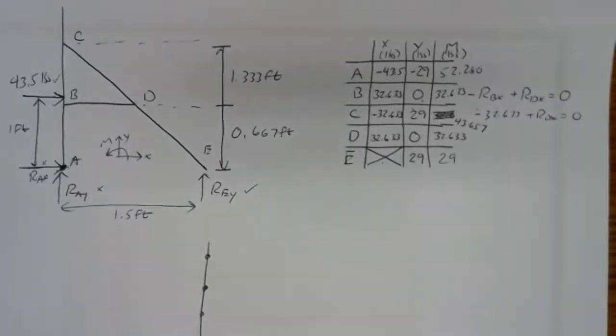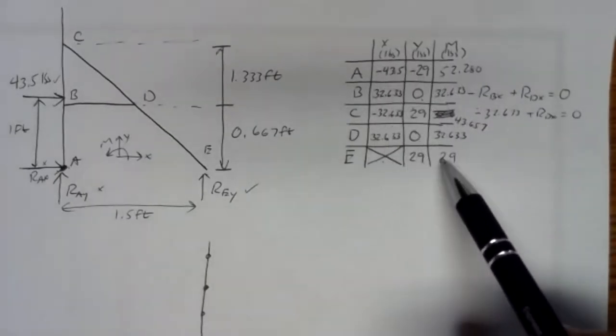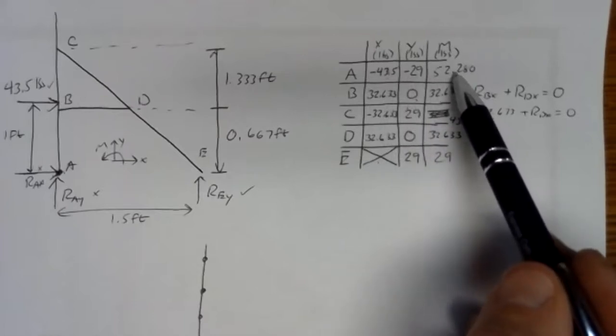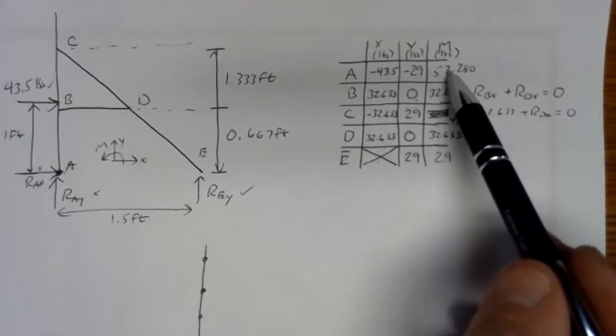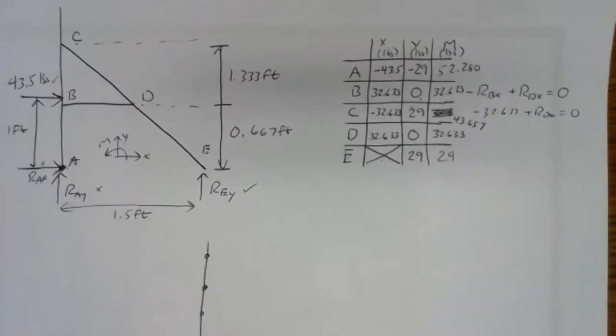Magnitudes should always come out positive, and they should always be bigger than the values that you put in here. One of the signs that you had some issues keying signs in is if you got a smaller value over here. Magnitudes always have to be bigger than the length of the hypotenuse of a right triangle. So that one's a little more complex of an example, but it can be worked the same way as the previous example. So if you're skilled at using free body diagrams, if you are able to handle the non-concurrent force problem, you're most of the way to being able to solve these problems.